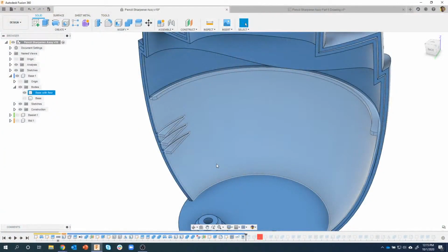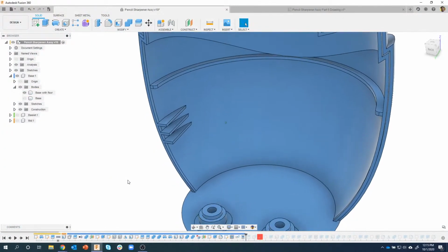Now, a lot of times you're going to have errors in sketches, errors in patterns and stuff like that. A lot of times you'll go into that sketch and the warning will say, a lost reference, reselect an edge or something like that. And that's all you have to do. Click on an edge. It now says, okay, I'm going to reference that edge, and it'll move forward. So just take a look at what the warning message is saying.